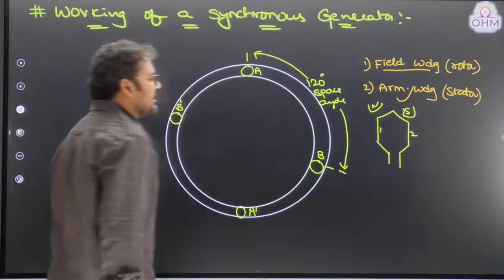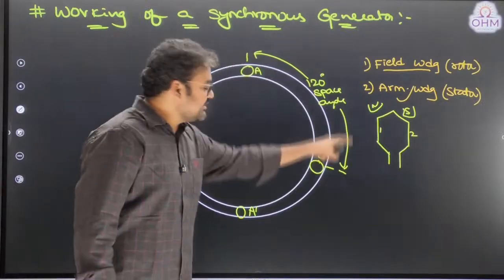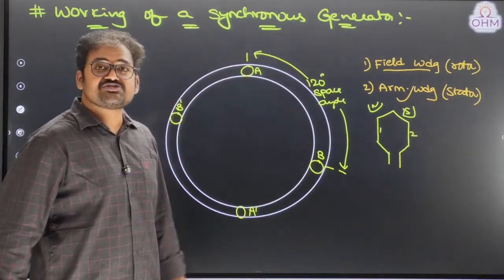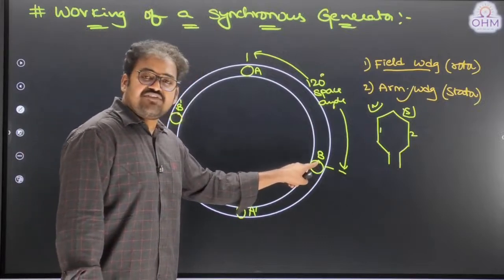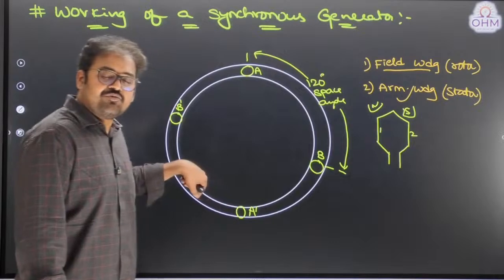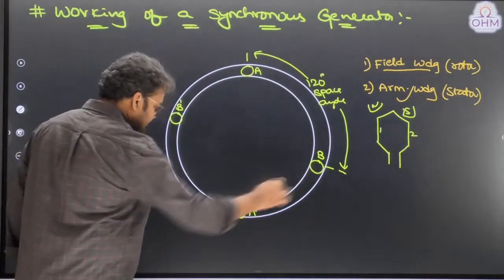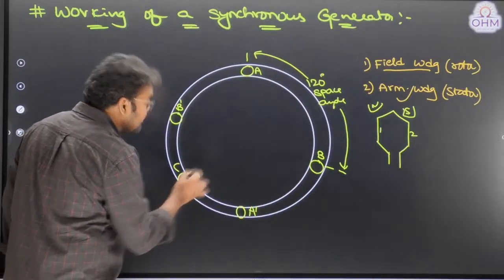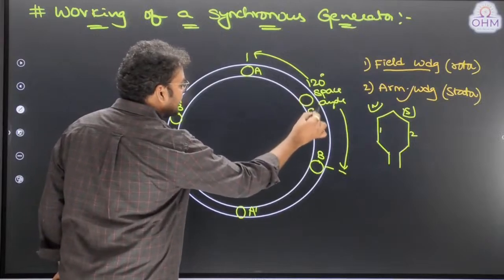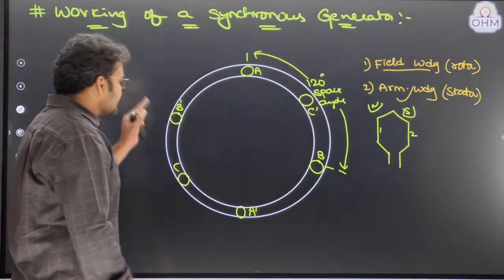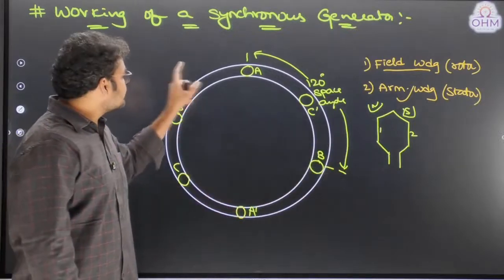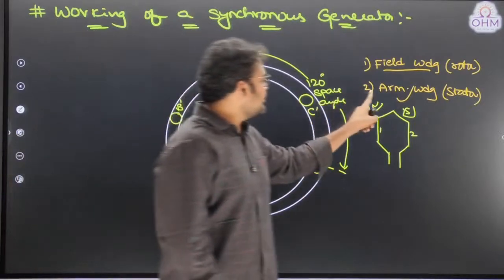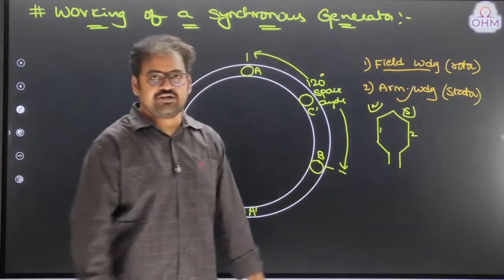Any physical angle that you are able to measure on the top of the machine, we call it as space angle. Now, if this is phase B, can I say phase C must be wound after how many more degrees? 120 more degrees. Here comes phase C, exactly opposite we have C dash. So this is a three-phase balanced distributed winding on the stator part of the machine, and we call that winding as armature winding.